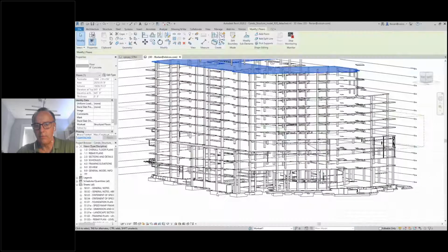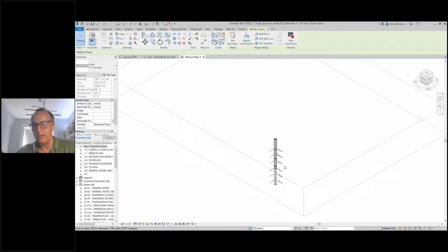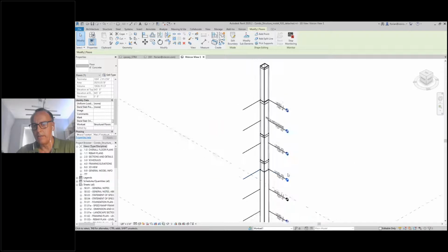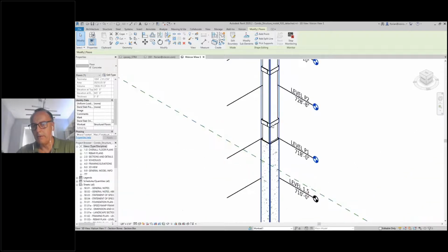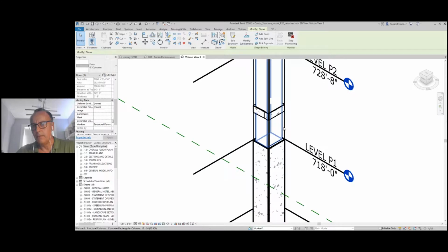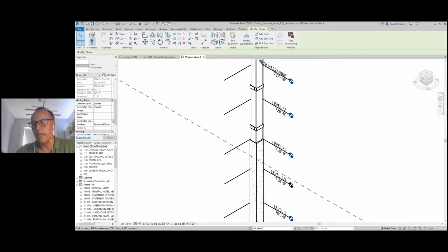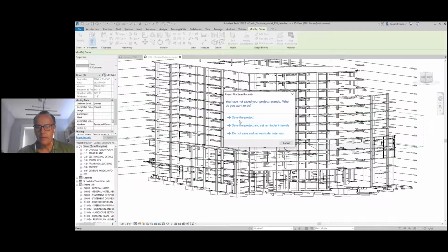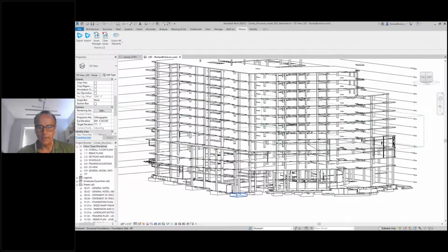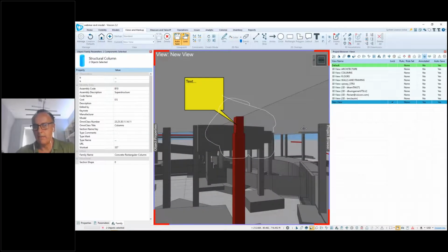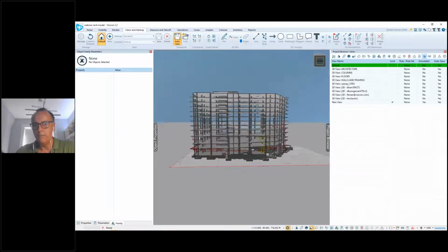Just simply reactivate your Revit model, and you see that column has already been selected, and I would be able to come in here and now make that adjustment, right? You see here, this column needs to come up to that level. It's that effective how you can increase and improve the communication between the markups or the comments that your engineering team is trying to pass on to the modeling team, right? So that's just a quick, simple example. And let's go ahead and cancel out of this, go back to Visicon. So that's markup. We're going to go back to our default view.